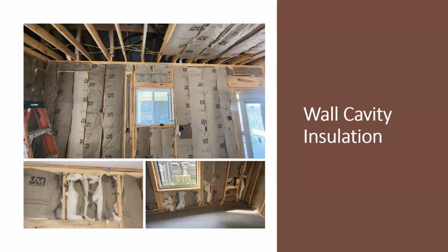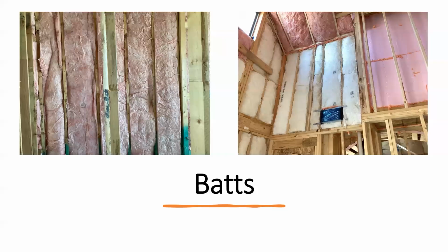Wall cavity installations, we saw these photos in a previous webinar that we did. These came courtesy of Michael with the city of North Richland Hills. So the two on the bottom actually were what it looked like before, and then he called it out and said, I need this corrected because it's not meeting what needs to be done for the installation instructions of manufacturers, especially with kraft face paper. It's so much easier to get a grade 1 by just stapling to the face. They were just trying to friction fit it like they did all the other batts that they used, and it wasn't done correctly. So the top of this actually shows it being corrected.